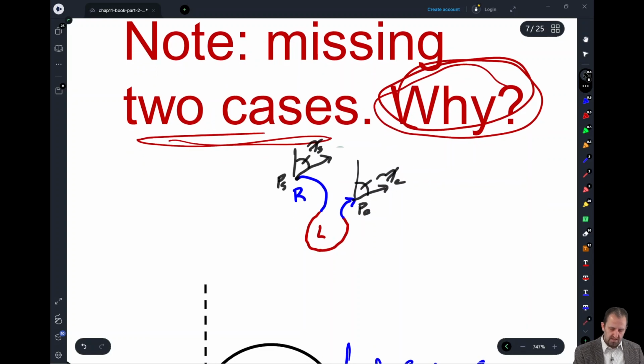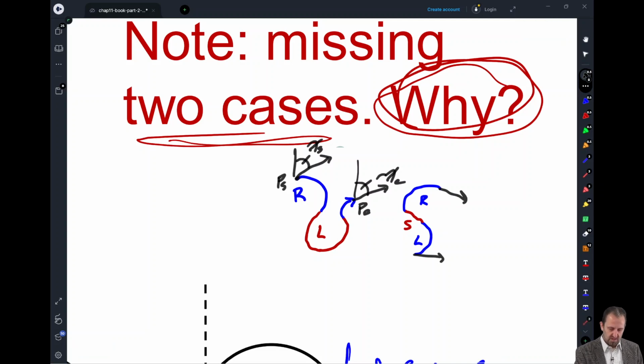And another possibility, and I can't draw the same Dubins path going between the orientations, so we're just choosing 2 different ending orientations. We could do a left, and then a small straight, and then we'll do a right. If I were great at drawing, I would have drawn them in the same exact configuration, but I'm not. So start and P end. What you should notice is that the distance between these is small. So we're just going to be following the minimum radius curvature on all 3, on both of these.